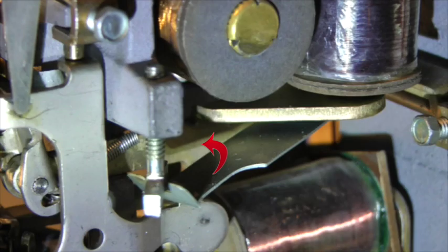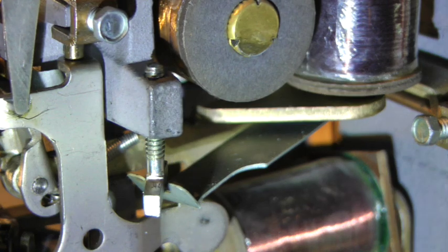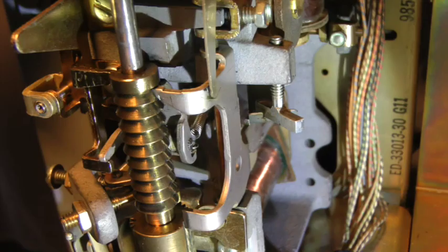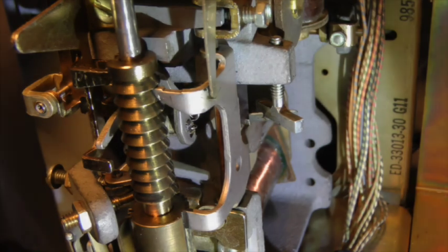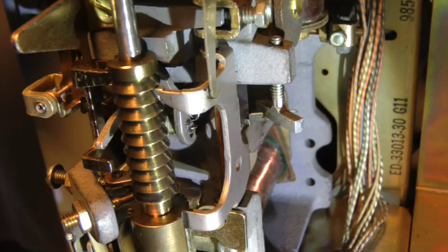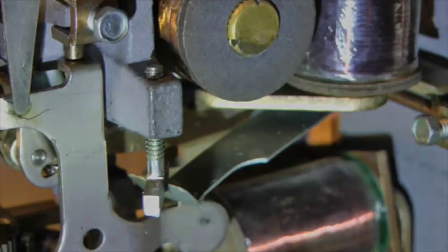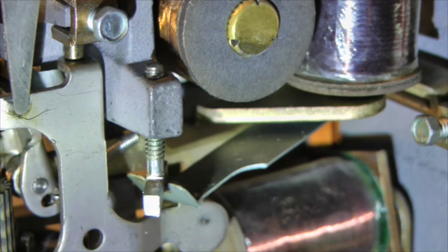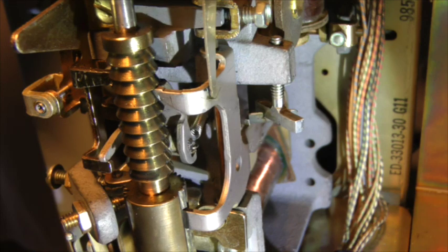Attached to an extension arm of this armature is a vertical pawl. With each attraction of the armature to the vertical magnet, the pawl engages a tooth of the vertical ratchet and forces it upwards by one step. Or, from a different perspective, with each release of the armature away from the vertical magnet, the pawl disengages from the vertical ratchet tooth. So each energizing and de-energizing of the vertical magnet steps up the shaft by one vertical step.